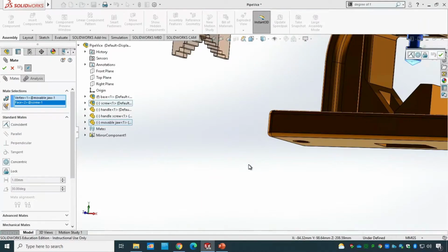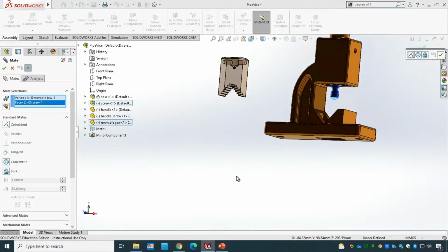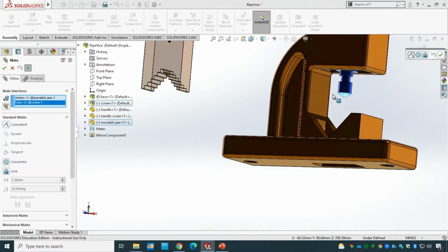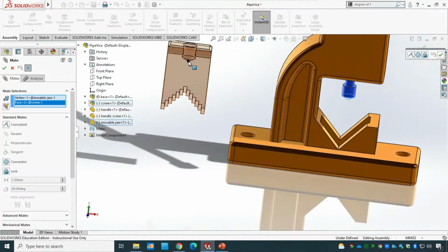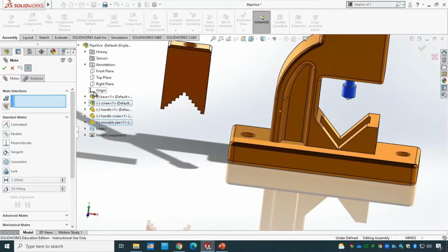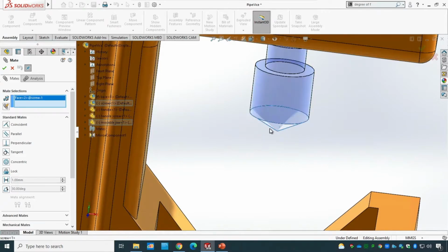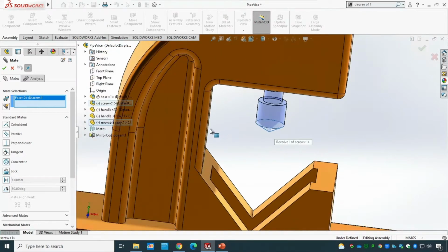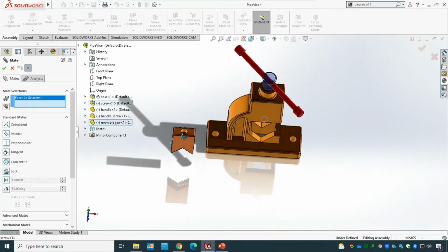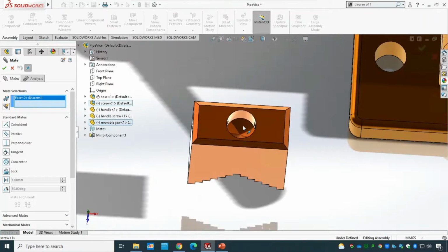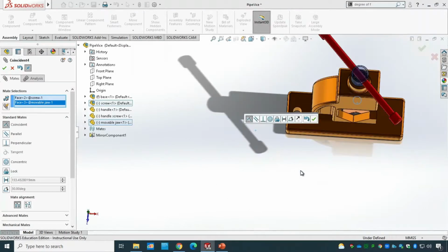what you will see is that if I put the coincident, it basically goes exactly there and will meet there. Let me have a look. This one is fine, but that one is for the vertex. Let me see. Vertex just picks up the exact point, whereas for here I want the full face. Let me have a look. This one is really important because the software is trying to find out what you're looking for at the back. Let me go quickly and pick up that face there. Yes, that's good.